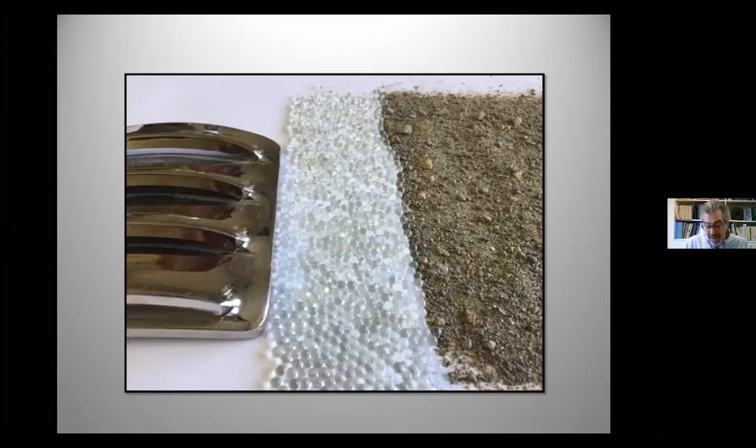Some will also add that if you're in a zone where you have a lot of bacterial problems that tend to clog up your screen openings and your local gravel pack, the bacteria won't adhere to these glass beads as readily as they would a natural filter pack, because the outer surface of the beads is so smooth, they just don't have a place to grasp onto. And then when you hit them with an agent, a dispersant, or an acid, they'll easily slough off.